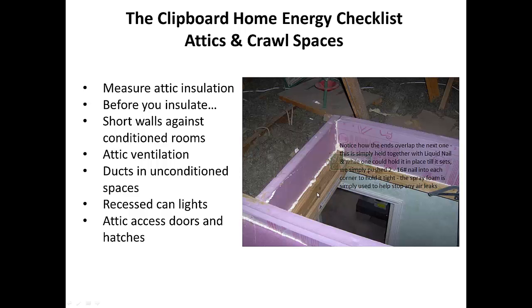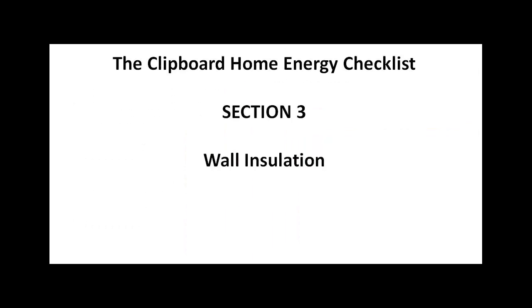Here is an attic access, and you can see there's the spring right over here where it's lowered down. And what they've done here is use just a couple inches of rigid blue styrofoam insulation, and they've caulked it with that foam caulk, those cans of foam like Great Stuff, so that when they add insulation they can get a higher level of insulation without it falling down into the stairway every time they open up to get into the attic to check something out.